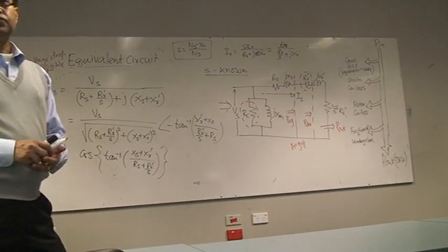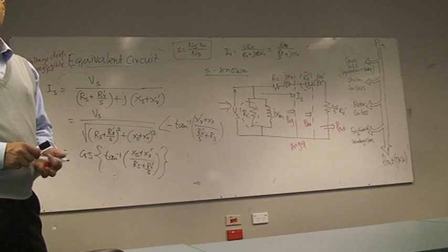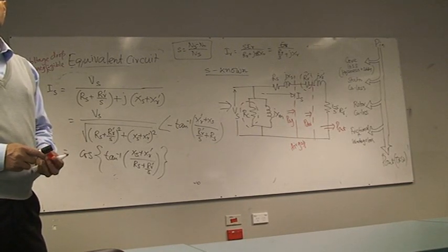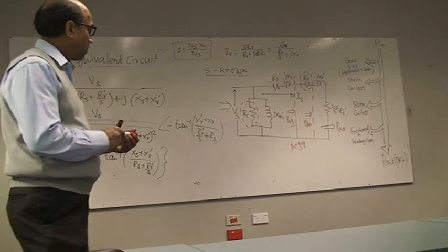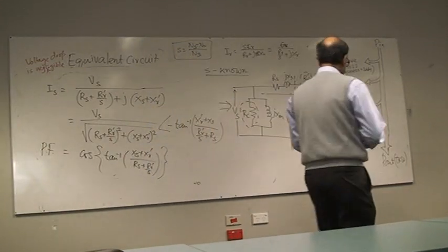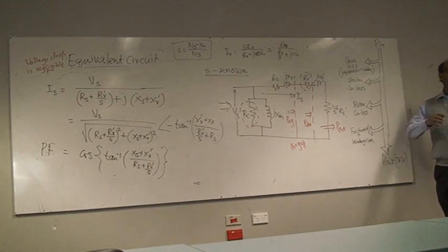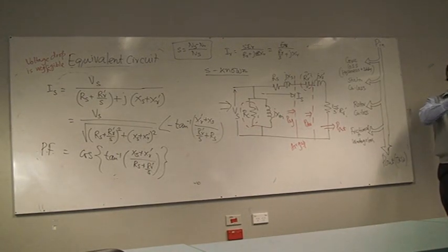So for the core loss, stator loss, and rotor copper loss, there are essentially three resistors that act on the current. Where does frictional and windage loss go? Where do we include that in that diagram? So frictional and windage loss, basically, you find that when you have two rotating members.